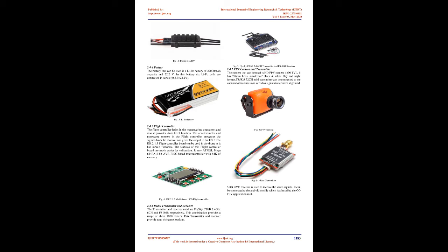A plastic tube of 1.3 meters length and 4 nozzles are fixed at 45 centimeters from each other. A pump is powered from a power distribution board. The inlet of the pump is connected to the storage tank and the outlet is connected to the plastic tube where nozzles are fixed. The landing frame of height 300 mm is connected to the main frame so that the landing of the drone will be safe and the storage tank will not touch the ground.